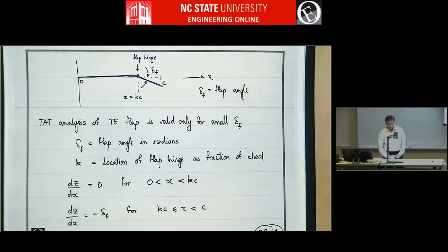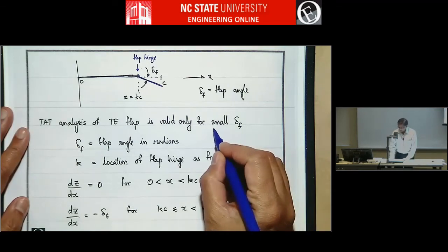So with this situation, we'll go and use thin airfoil theory to study this. But we have to remember that thin airfoil theory is really valid only for small camber and any kind of small geometry deviation. So it's really only valid for small flap angles.